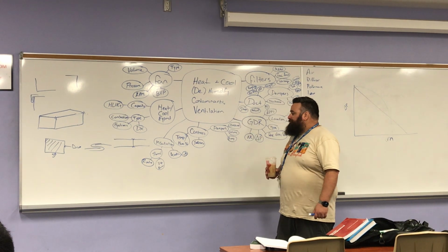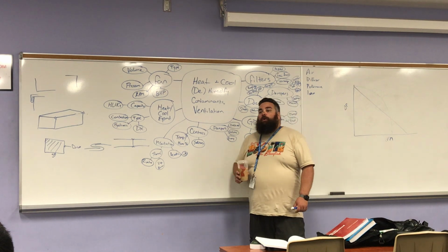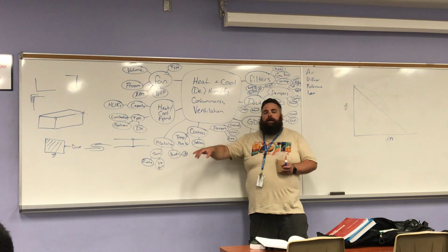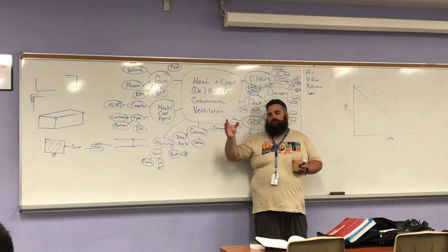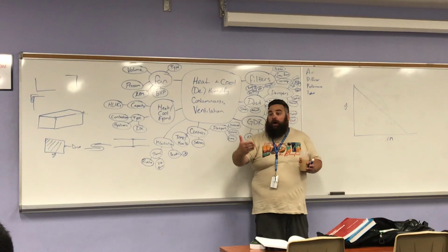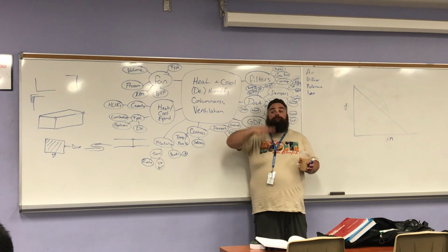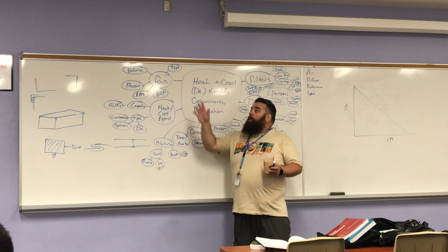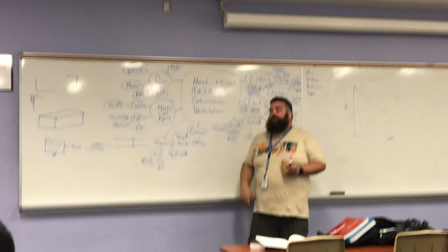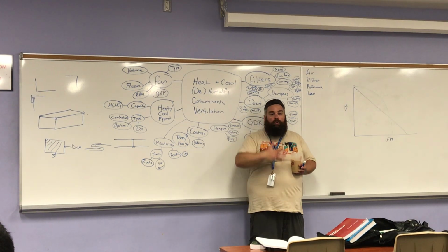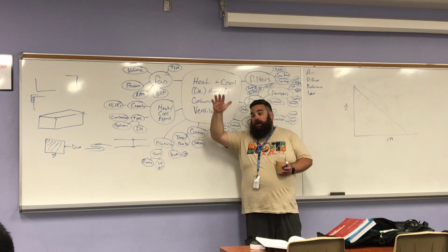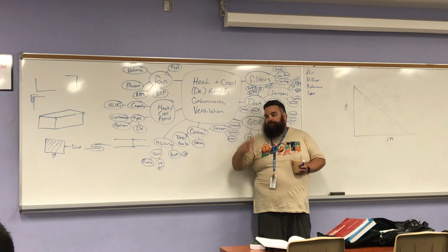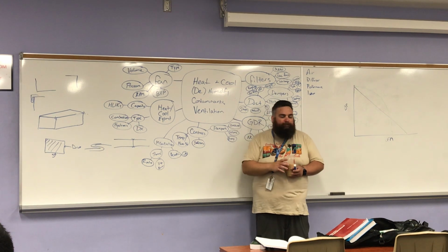Can you not install it externally? Well, no, you can't, because part of the reason we put acoustic insulation is, think about the sound vibrations, right? When I'm talking to you now, what you're hearing is my vocal cords vibrating the air, coming to your eardrum and vibrating your eardrum, but it's also bouncing off of the hard surfaces. That's what happens in our duct. We generate noise and it bounces off those duct walls. So the acoustic lining goes on the inside, so it starts to absorb that noise rather than bouncing it.